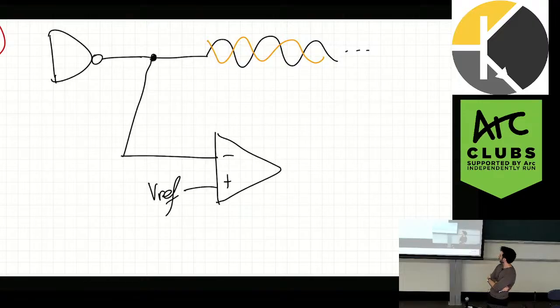So the other solution is to use a latch. And what would you use with the latch? Some kind of RC timing, like a simple unstable multivibrator. Yep. So this is bouncing off the same solution you just had, but taking it a little further: we could probably use something like a Schmitt trigger with some hysteresis, right? The reason a Schmitt trigger with hysteresis is good is that we can then use an RC time constant network to charge and discharge between these hysteresis levels when a change is happening, right?